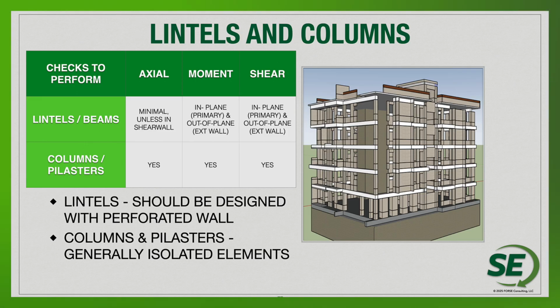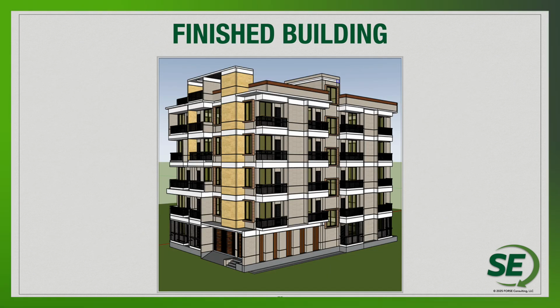Columns and pilasters, obviously, we're going to have a lot of axial force generally coming down for those elements. So even if we have relatively high moments or lateral forces, we know that we also have a good helping of axial force to keep us on the curve.